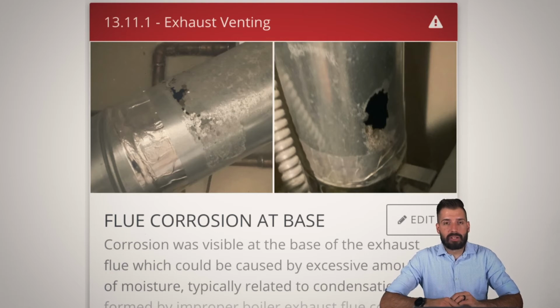And on this particular one, we inspected the house, and then the individual taped over top of this with tape, and it was foil tape. And then they were hoping that a different inspection company who didn't already inspect their house wouldn't notice. And it's like, man, replace the metal flue. You're going to kill somebody. Just replace the metal flue.